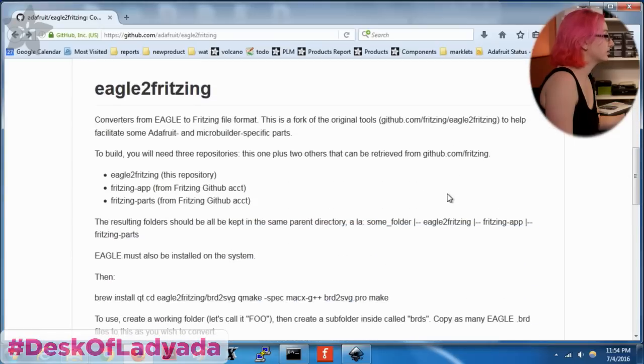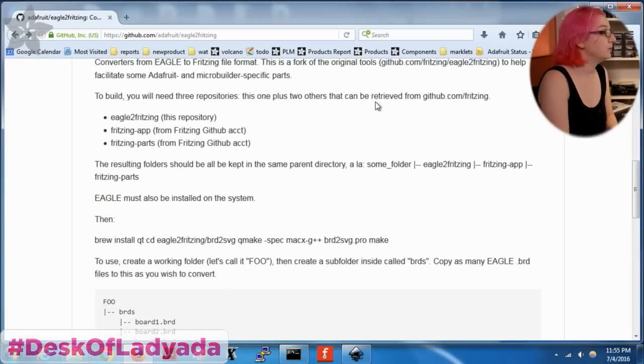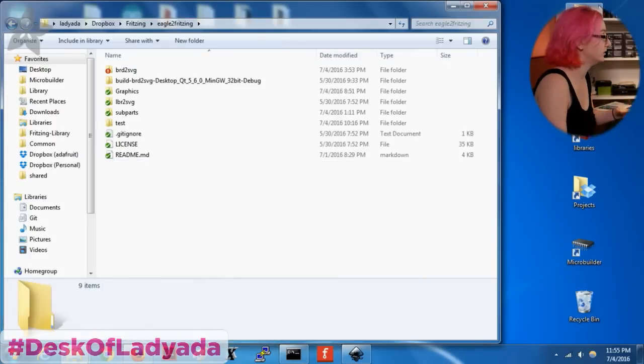Basically it can take an EagleCAD BRD file and it converts it to an XML file and gives some manipulation. So you could use this with KiCad, you would just have to figure out how to convert the KiCad XML into this XML. And then it will actually locate all the components and draw them into an SVG. This was like three weeks of effort to get it to do this. So Phil B did an amazing job.